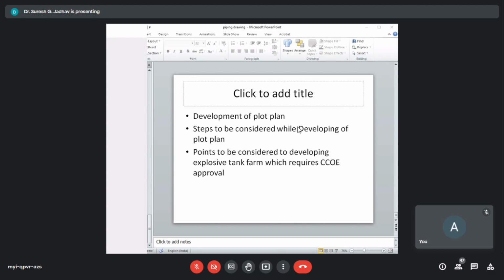Two adjacent process units shall be located based on the annual shutdown philosophy so that hot work shall not affect the operations. Process units shall be located on higher ground away from unwanted traffic. Process units shall be serviced by peripheral roads for easy approach. The utility block shall be kept in a safe area close to the process plants. Electrical substation shall be placed at the load center to minimize cabling.